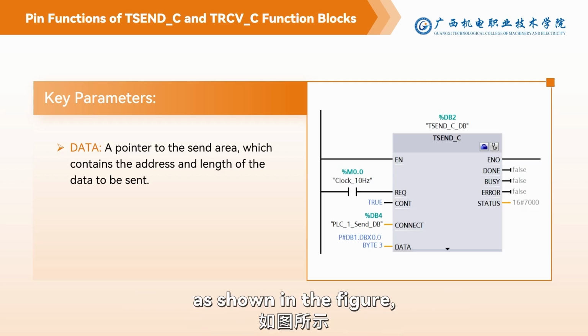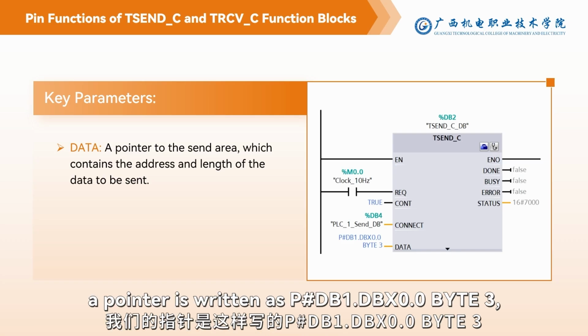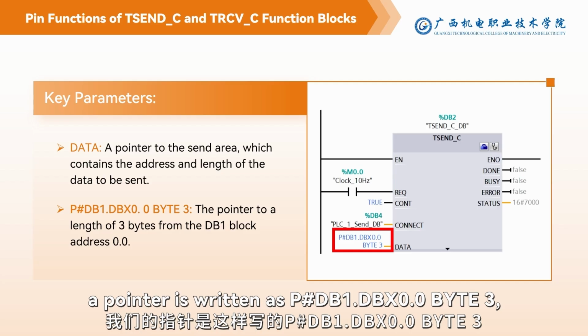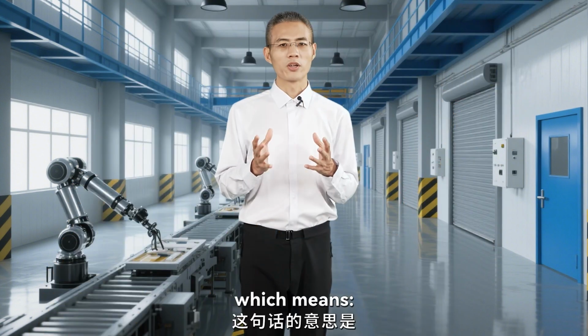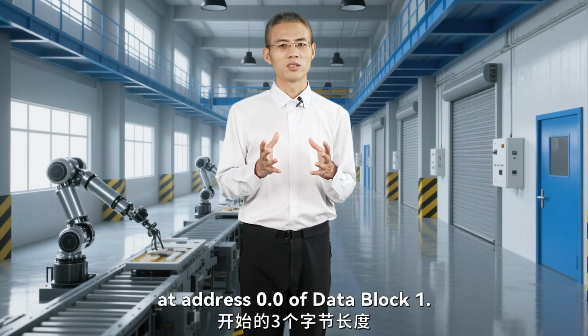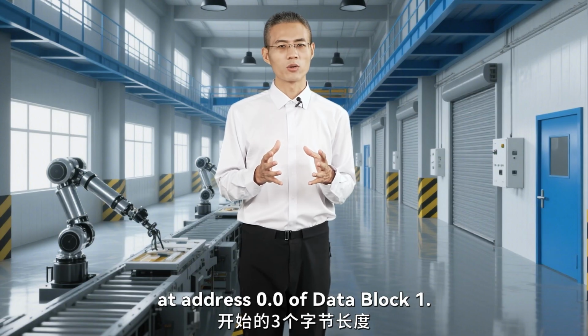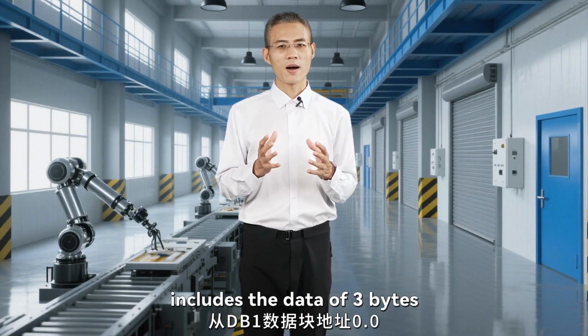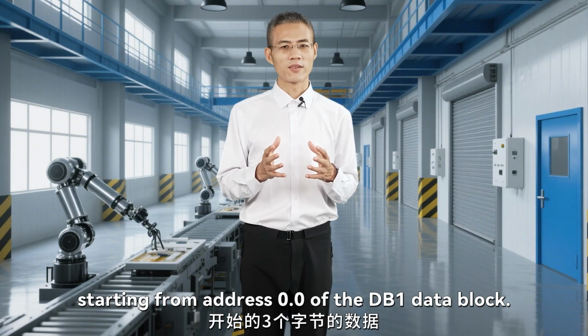Specifically, as shown in the figure, a pointer is written as P#DB1.DBX0.0 BYTE 3, which means the pointer points to 3 bytes starting at address 0.0 of data block 1. Thus, the send area includes the data of 3 bytes starting from address 0.0 of the DB1 data block.